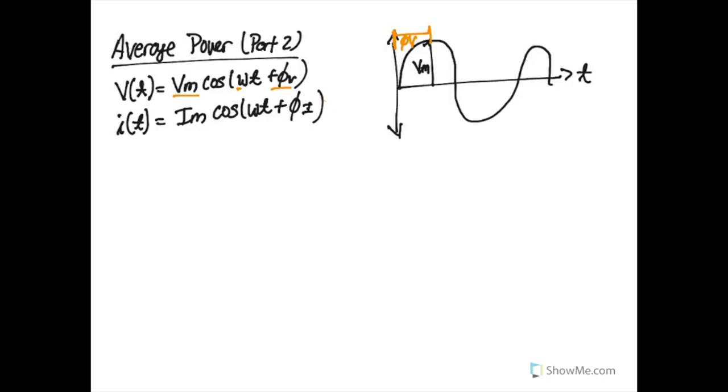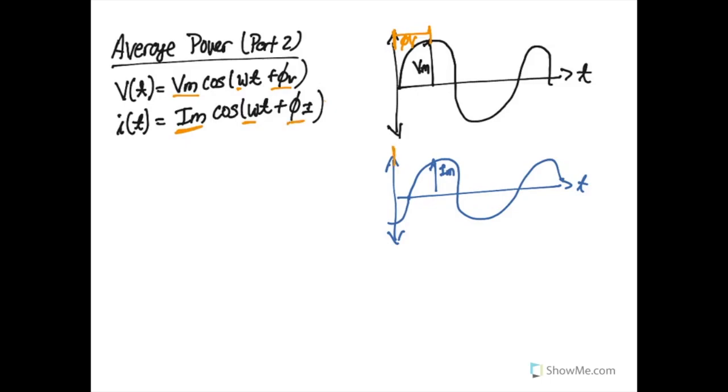And in the same way, we can have a current function as well. Just like with our voltage, it would be something over time. Let's maybe make it come in at a little different time here. This would be our current function. And our current would have a magnitude as well. It would again have its own magnitude, its frequency, and again its own phase. And that would be the amount of time from zero to a peak of the current function.